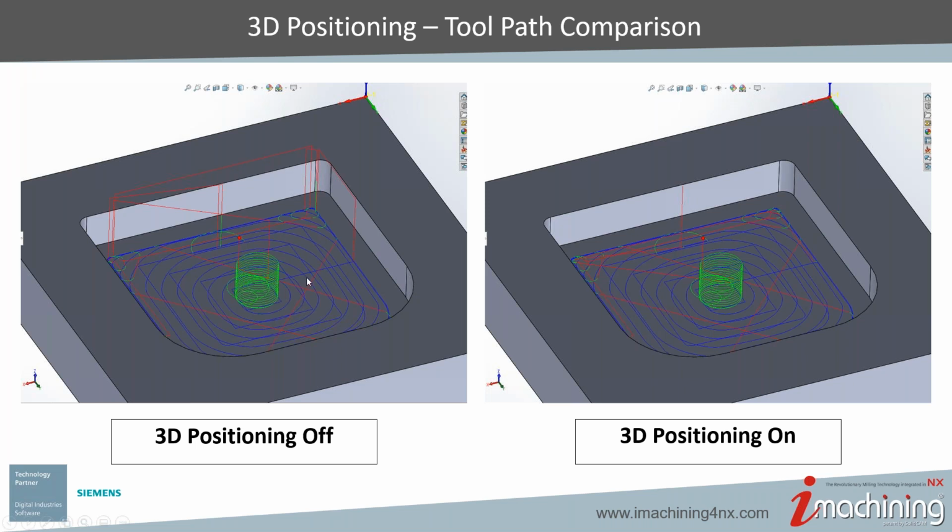But if we look at even just a simple roughing and finishing toolpath, here we have a toolpath which is roughing and finishing. You can tell it's finishing because it's also finishing the floor with the contour strategy, so you can see the floor offset passes. As we know with iMachining finishing, we clean out the corners and do a finish pass. Here you can see there are 6 or 7 repositions where the tool is returning to the clearance plane, wrapping over, and wrapping back down.